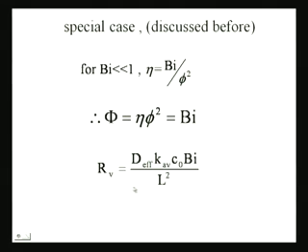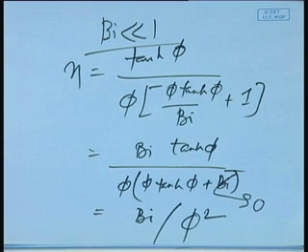So what it means is that the observed reaction rate, what you observe, is dependent only on the external mass transfer. So whatever is the rate of external mass transfer is the rate of reaction. So if you have 3, 4, 5 or n number of processes in series, that is the most important thing, and if one of these processes is limiting, then the rate of the overall process equals the rate of the limiting process, right, something you know.